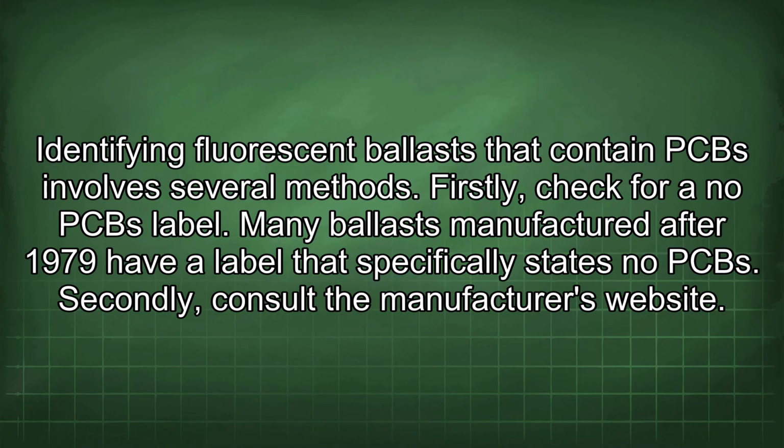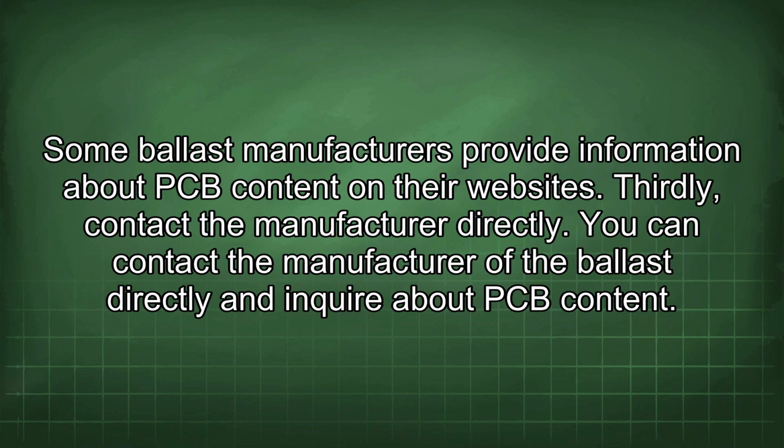Identifying fluorescent ballasts that contain PCB involves several methods. Firstly, check for no PCB label. Many ballasts manufactured after 1979 have a label that specifically states no PCB. Secondly, consult the manufacturer's website. Some ballast manufacturers provide information about PCB content on their websites.